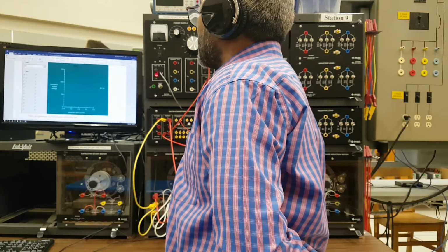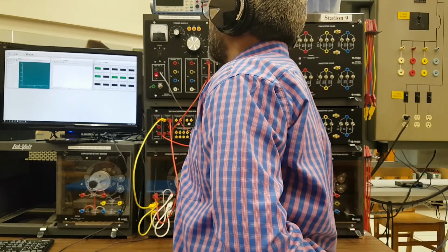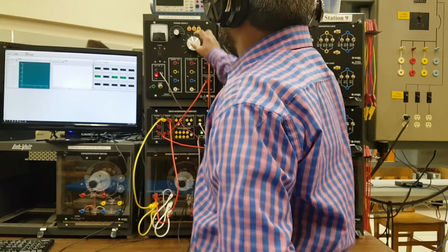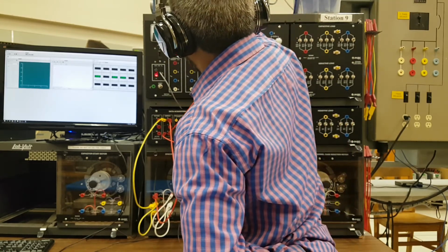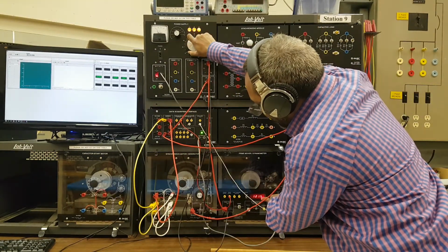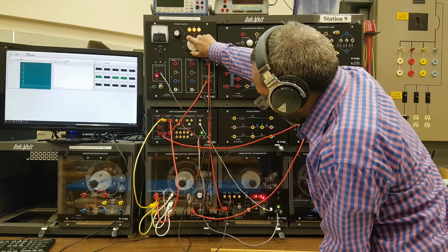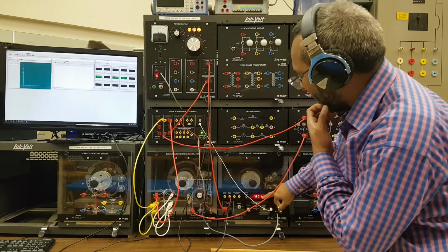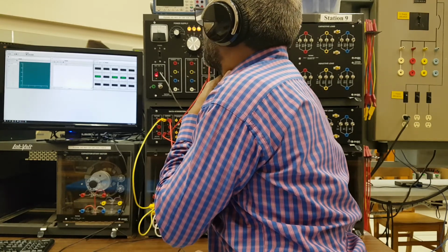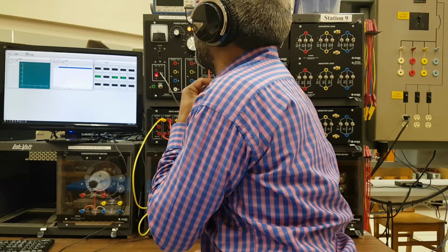Where is that? Here. Okay, so right now it's 0, so we have to activate this one. I1 we are measuring, short circuit current, that is there. Field current, we will run the machine at 1800 rpm fast. You can see that the speed is increasing. It's increasing. We have set 1800, so it's 1800 rpm here. So we just take the reading at null current without any field.